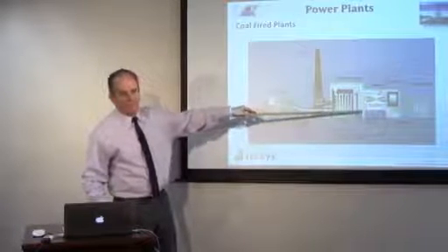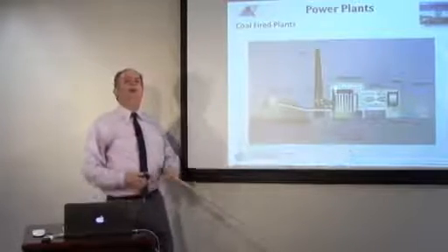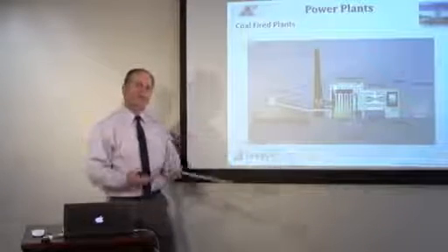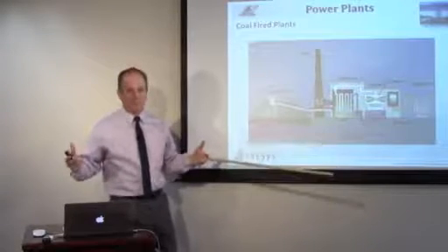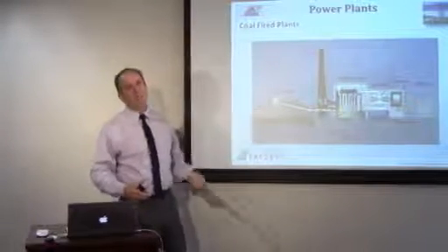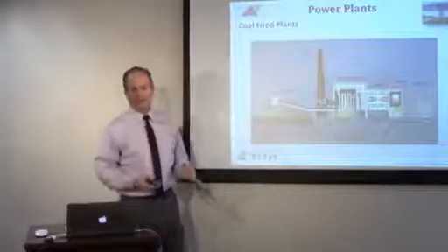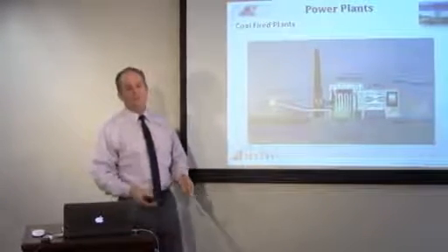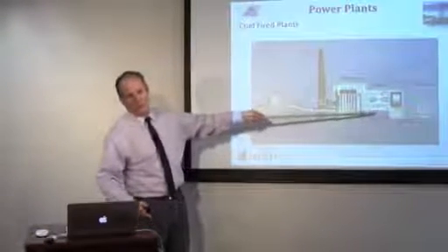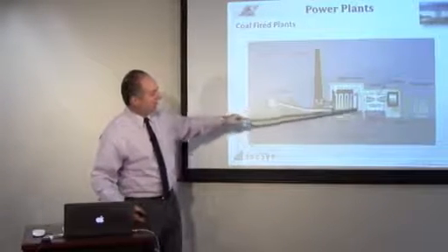And the steam, after being used on the blades, the high pressure steam goes into a large volume, so the pressure is going to drop because it goes into a larger volume area. Pressure drops. We're taking the high temperature steam and spinning the blades, and the temperature of the steam is going to drop. The pressure drops, the temperature drops. We come through here, and now we have a lower temperature, lower pressure steam that we condense